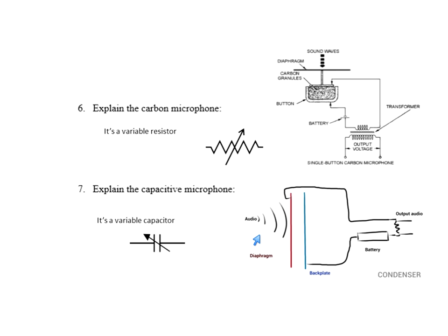Now, capacitive microphone, look at it right here. A capacitor is built with 2 plates. A capacitive microphone works like a variable capacitor, but how does it work? Well, here's one plate separated by an insulator, and here's another plate behind it. So what happens here is when I talk into this condenser microphone, it makes this plate move closer together or further apart from the other plate. And remember, that's how capacitance changes. So a condenser or capacitive microphone actually changes its capacitance according to the sound waves. So that one acts like a variable capacitor.